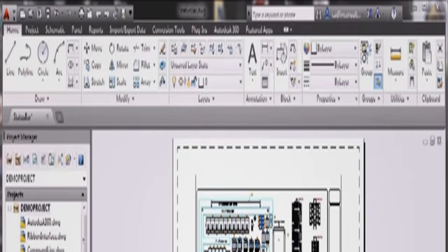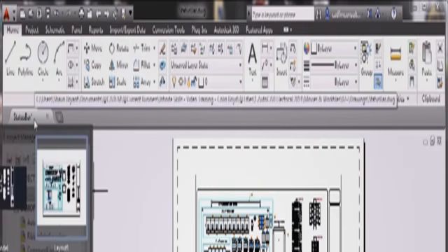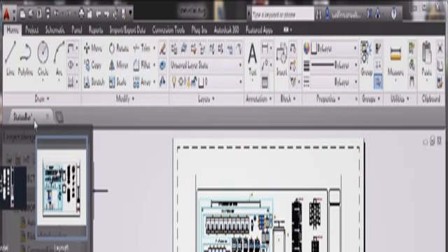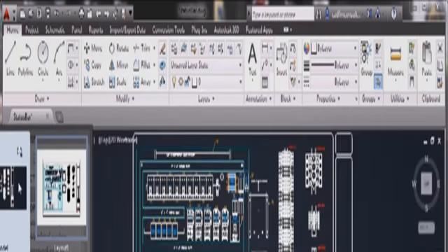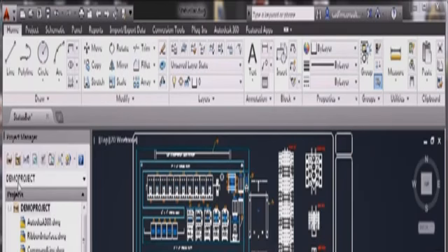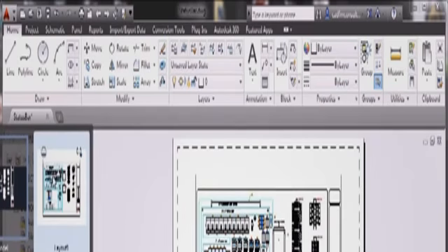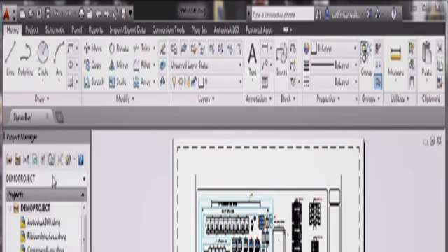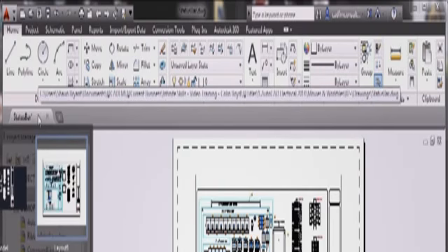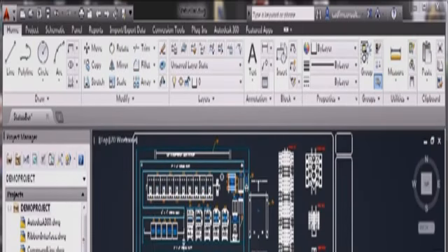Now you can also switch on little tabs that appear here. But also there's a new feature now in newer versions of AutoCAD. The drawing tab is up here. If I hover over it, you can see there's layout and model there as well. Just go slightly off the screen there due to my screen resolution, but don't worry. I can just hover over model there and click, takes me into the model space. If I hover over the status bar again, hover over the layout and click, takes me into the layout space. The nice thing about that is if I hover over that tab, model is always there and any layouts that I've got set up are always there.